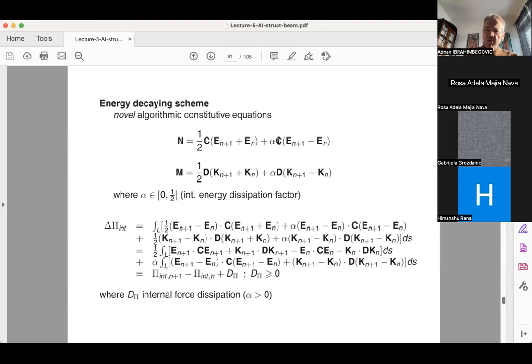So the time step for a fundamental mode could be typically just a fraction of the period. And basically you will have a very small correction to En minus En plus 1. On the other hand, if you have high frequency, this is a very large value of omega, and so 2 pi divided by a large value will be a small value. So for a high frequency where you have a small period, the difference of these two could be quite significant. And what you're doing with this, you're basically taking it out.